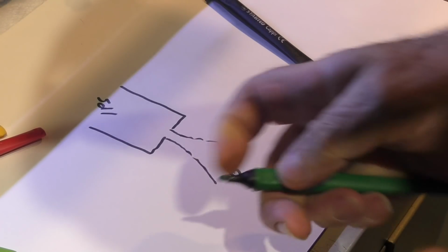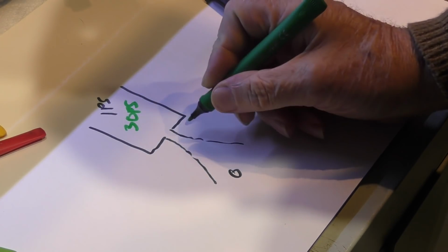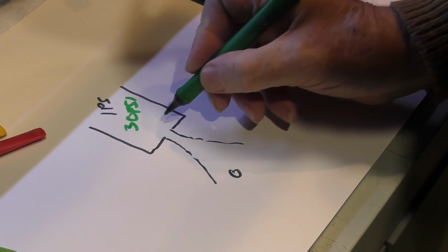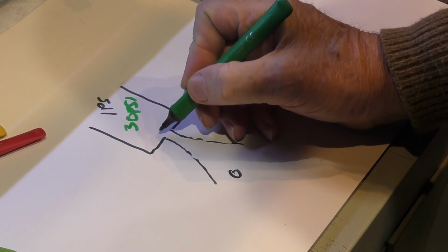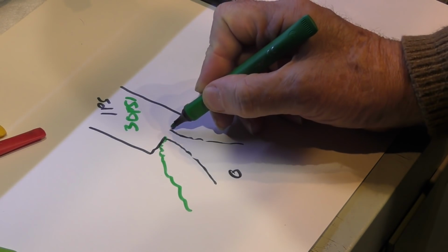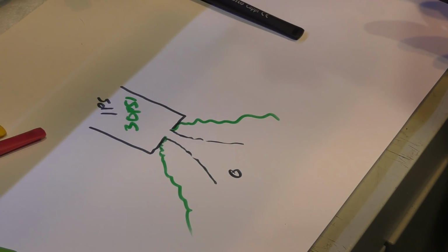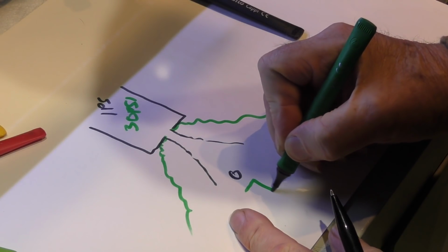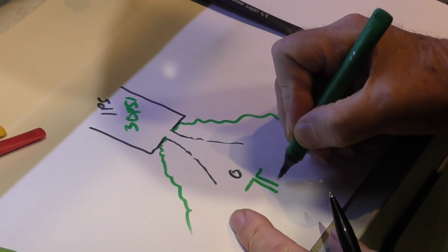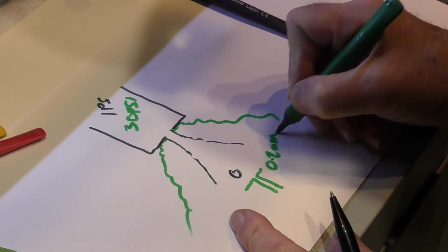If, as some people claim, they're using about 30 psi, then what's going to happen is 30 psi across this orifice is immediately going to do this. It's going to climb out here and it's going to expand as rapidly as it can. We've got a kerf down here which is 0.2 millimeters wide.